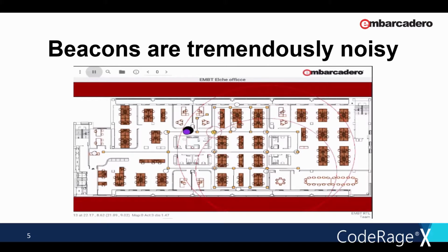The signal from beacons is tremendously noisy, especially indoors. Radio signals jump and bounce around constantly. Walls, electrical devices, electrical wiring, different mobile devices, Wi-Fi, and even people result in absorption, interference, or diffraction of the signal. So the beacon standard is not primarily designed for indoor positioning. It is, in principle, focused on proximity. A really advanced noise smoothing algorithm as well as some recommended practices are needed depending on the purpose of our BeaconFence application.